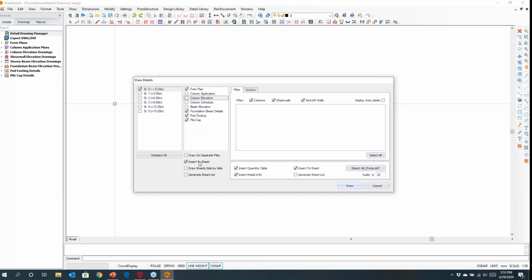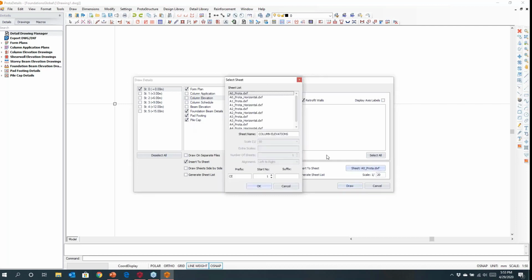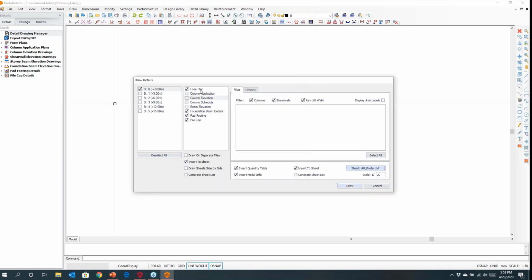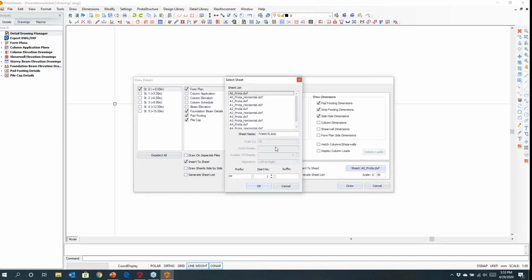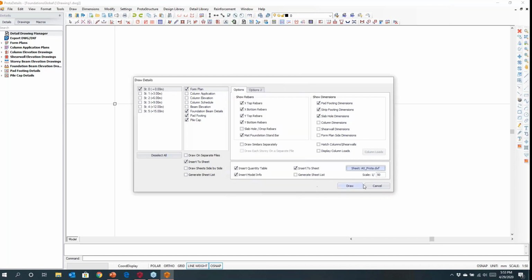Now these can be automatically inserted to your sheet, and you can just come and predefine the title block here. Now, you can come and set up different parameters. So for the sheets, you can create naming conventions. I may want to call this bottom drawing here foundation plan. It's up to you. You can just come and set that in here. And you can play with other things like scales and details and so on can be set here as well.